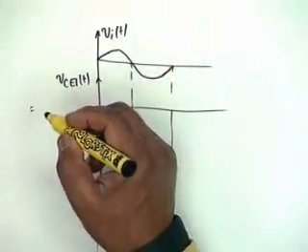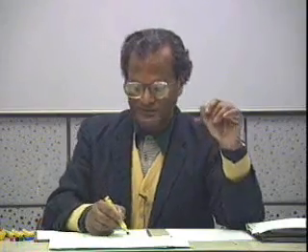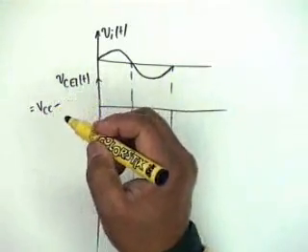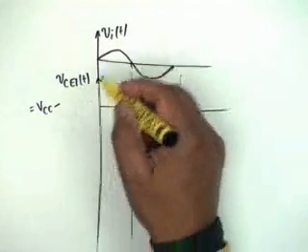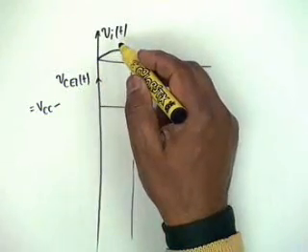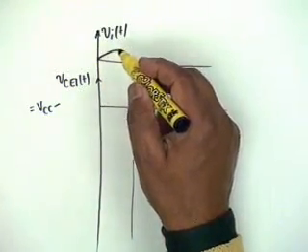VCE1(t), the collector emitter drop, if you recall the circuit, would be VCC minus VO of t, but VO is approximately equal to VI if you ignore the VBE1.